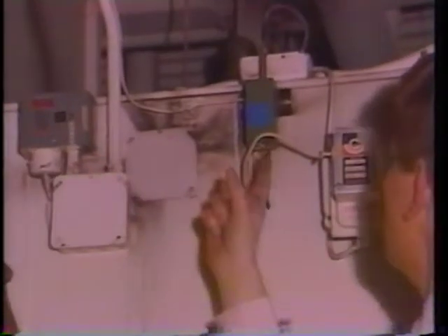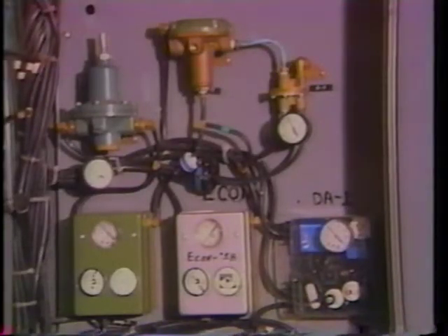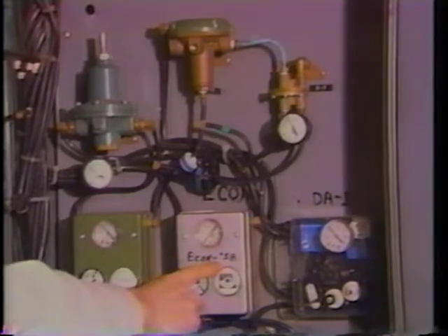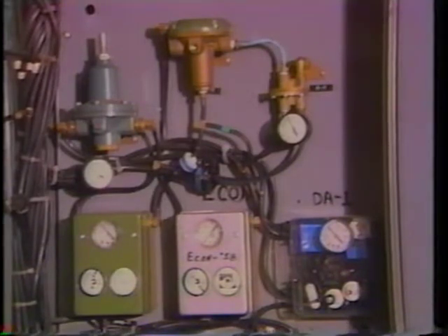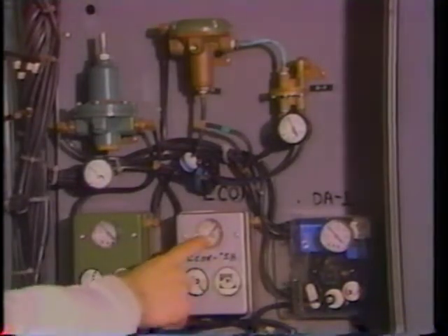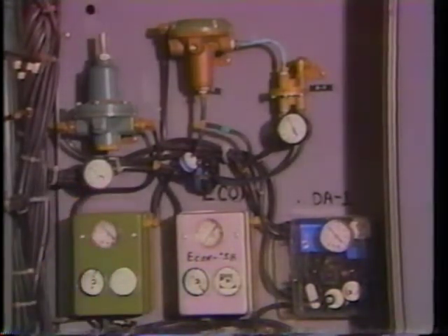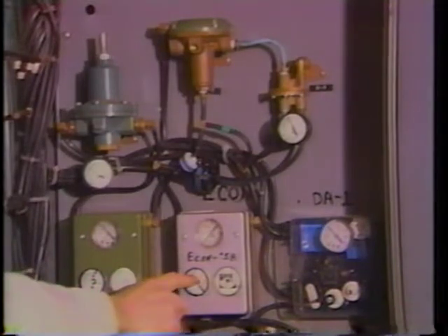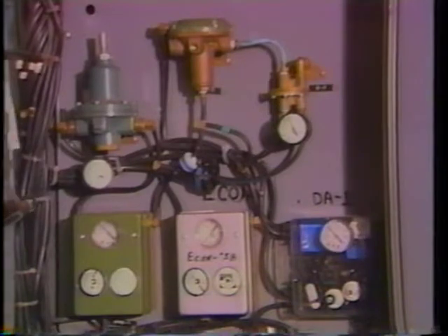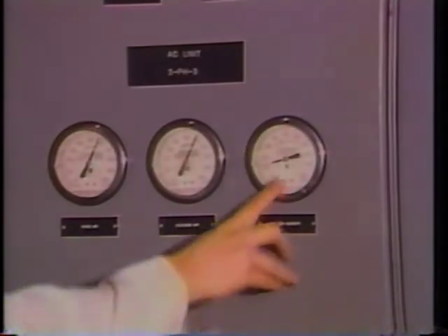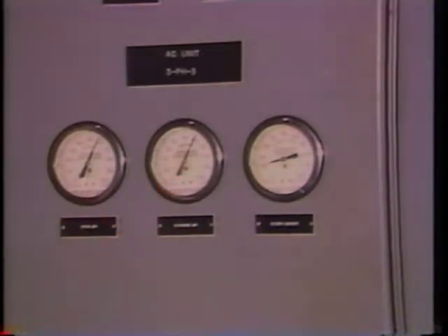Because the controller doesn't have to be located at the point of measurement, it can instead be located in a central control panel, along with all the other controllers, relays, and auxiliary devices. This is especially helpful for monitoring during troubleshooting, when it's necessary to know the status of several different variables and control signals at once. Also, all of the set points and adjustments for the whole system can be localized in one panel, rather than having to visit each individual conventional controller location. From this location, I can see every individual controller output and input.